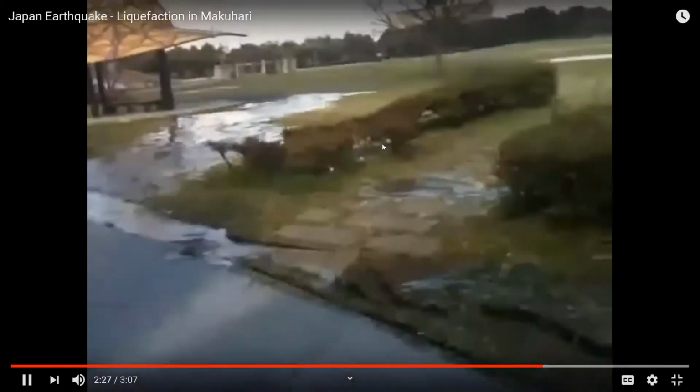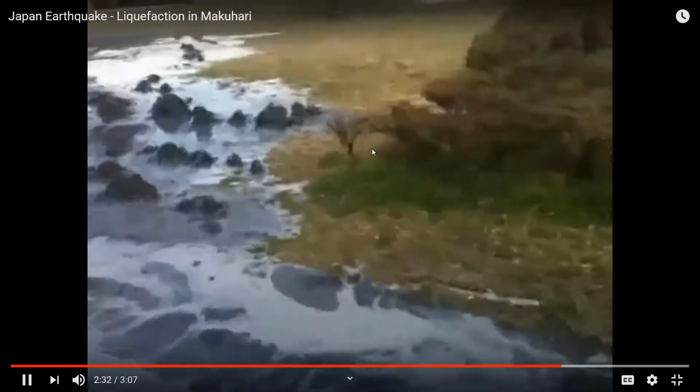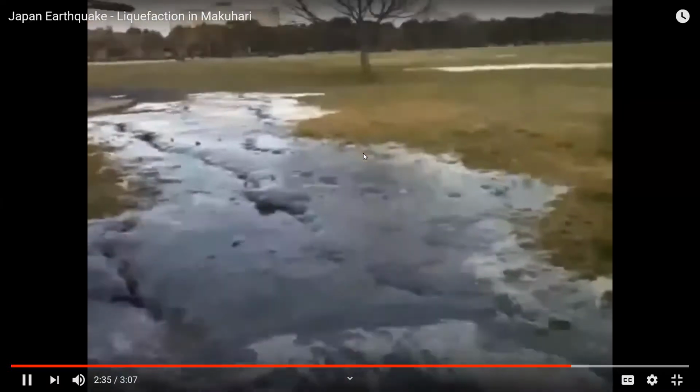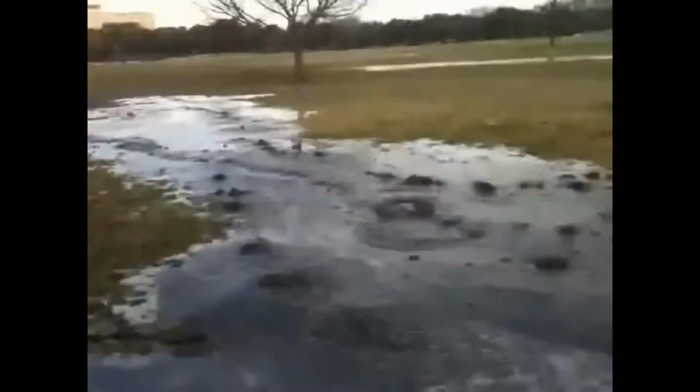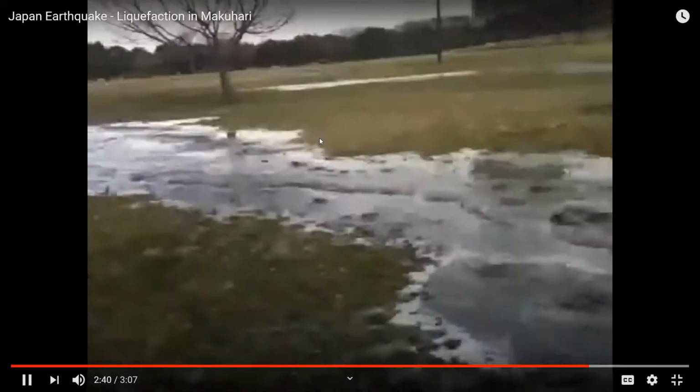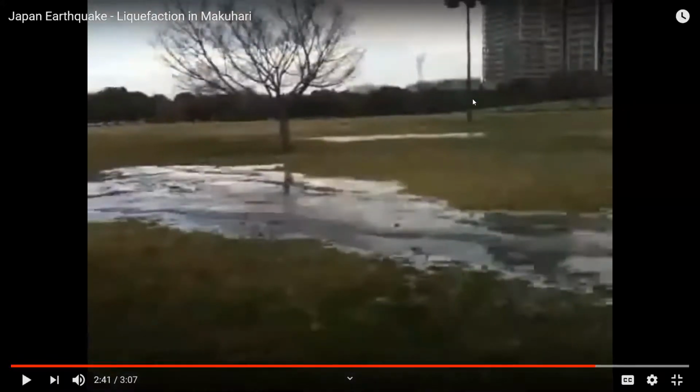Especially since this is reclaimed land that I'm on right now. This used to be part of Tokyo Bay, and they created this land by throwing landfill and mountain rocks out here. And so this land could potentially go. I don't know. Okay, the land's not really just going to go, but that is why the liquefaction is occurring here. It's soft sediment. It is infill, right? They're creating new land in Tokyo Bay by pushing a bunch of dirt and rock and stuff into the bay to create more habitable land. But that is why the liquefaction is occurring here.